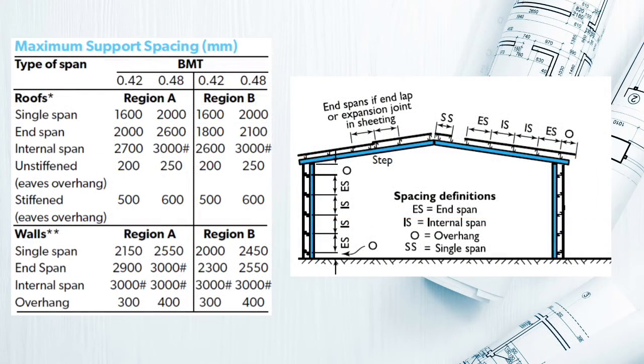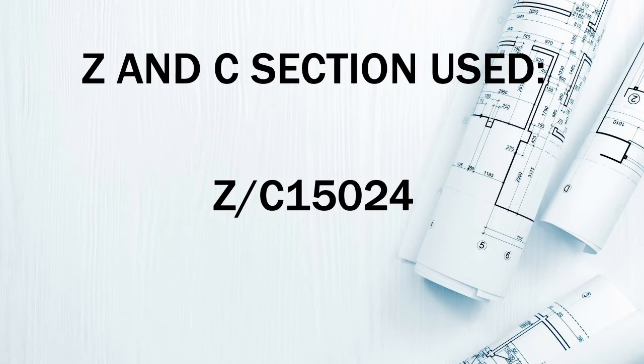Purlin spacing was set by the requirements of the roofing materials used in the user guide. The Cliplock Classic 700 was used as a guide in relation to using 0.42 BMT roof material. The purlin and girt spacing depends on frame location, wall cladding spacing and roof sheeting. The girt and purlin size were chosen for a 5.4 meter span and a 1 kilonewton per meter wind load.